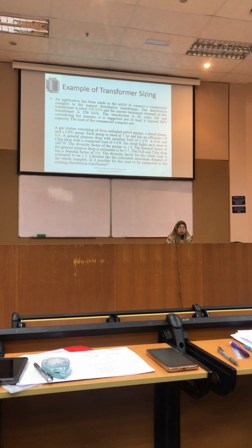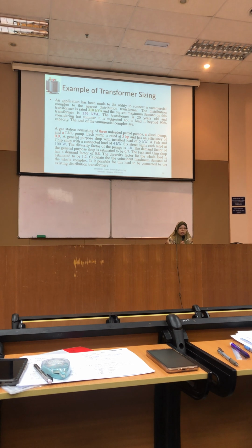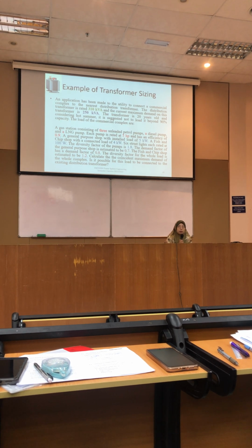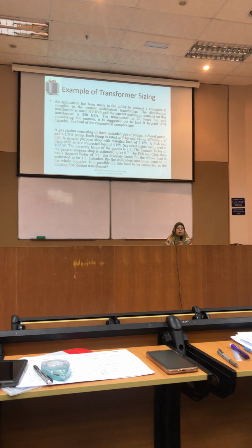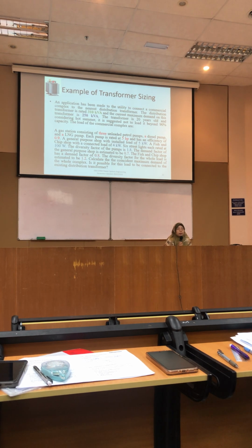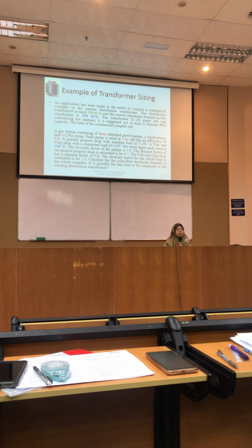The transformer is 20 years old. Considering the hot summer, we need to make sure that the transformer is not overloaded. It's suggested not to load it beyond 90%, due to the hot summer.